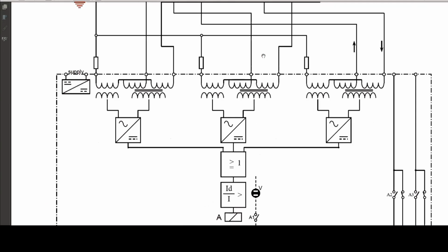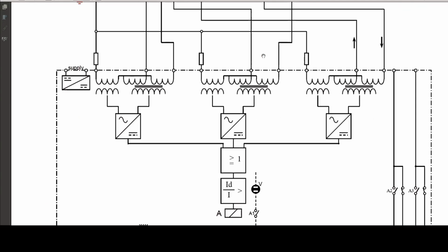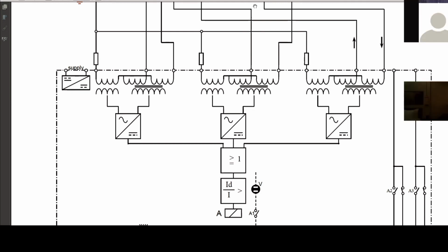Of the differential protection, because at an internal fault, for example, red phase and yellow phase are short circuited, or if due to any reason the red phase has been attached with the ground or the core, in either case I1 minus I2 is not equal to zero. So then that current will be passing or flowing through the operating coil. And one more thing is that the two different phases.